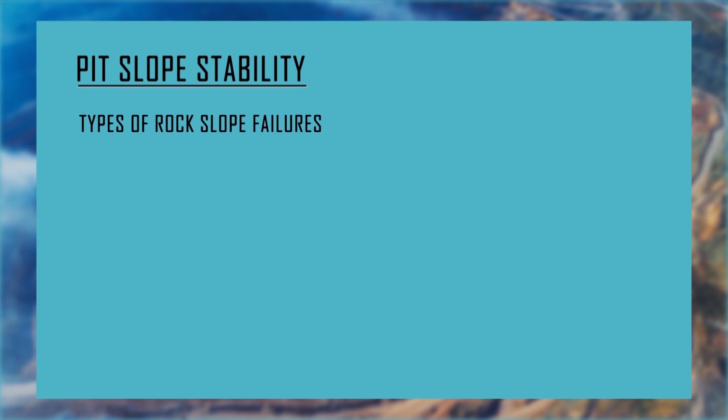If the factor of safety is below 1, then we take remedial measures against the failure of slope, and these include bolting, draining of slope, and control blasting, etc. Here are the possible failures of benches in open pit mines.